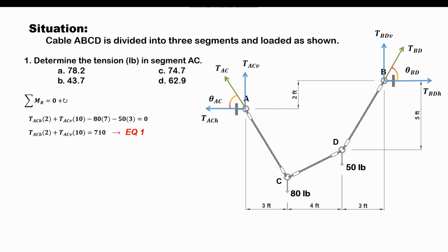But if we were to use those equations of equilibrium considering the whole structure, we will be involving the unknown reactions at B, and we don't like that. We only need an equation that involves the reactions or component reactions at A. So basically, summation of moment will be the equation that we will use again to generate the other equation that we need. But how?